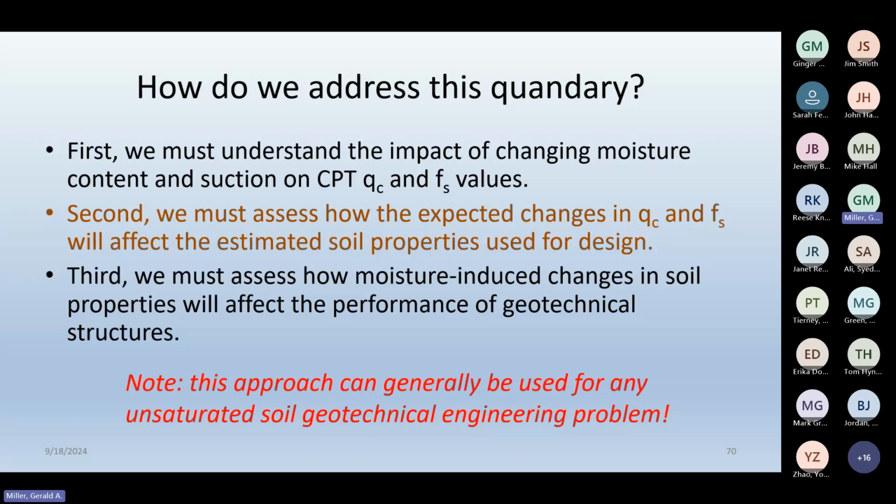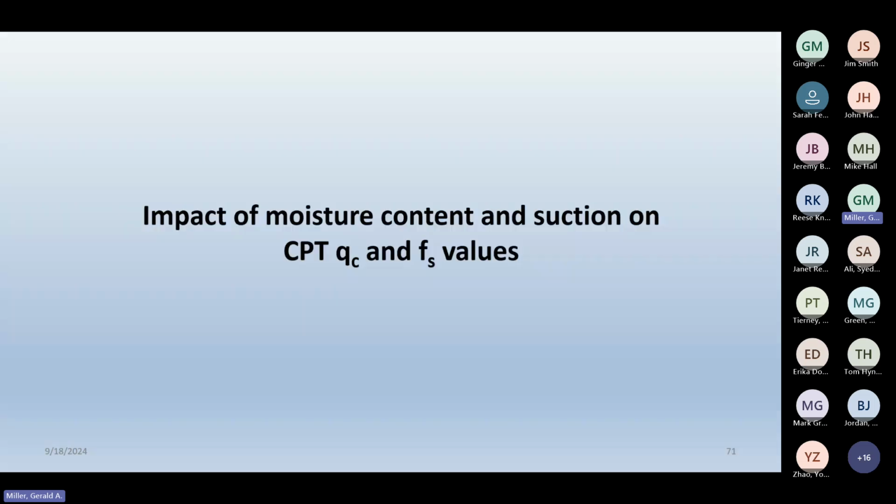So whether it's slopes or footings or pavements or whatever, you need to think about how changes in moisture content are going to affect our analysis, and then how the interpreted soil properties based on our in situ tests are going to affect our analysis.